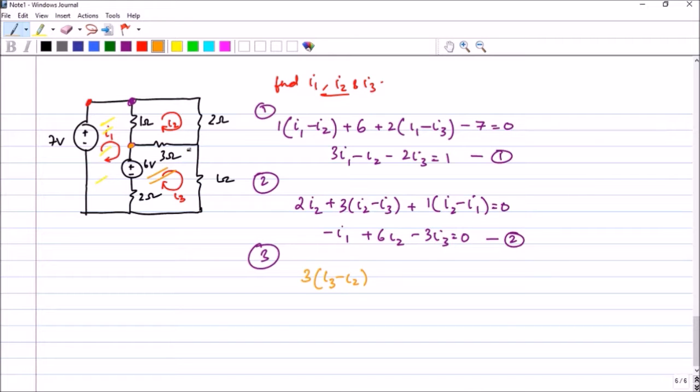All right. Then I come through the 1 ohm resistor. So that is exclusive to the third mesh. So 1 into I3. And look at now, I'm entering like this through the 2 ohm, but I1 is opposing. So I get plus 2 into I3 minus I1. Then I enter the negative. So minus 6 equal to 0. So if I simplify this, what will I get? I will get minus 2 into I1 minus 3 I2 plus 6 I3 equal to 6.